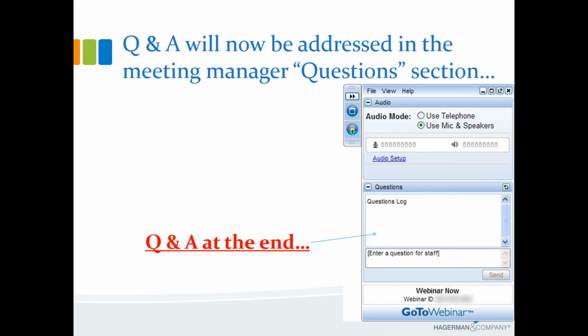Also, if you do roll them up and then you come back after you do that and you make an edit like I did where I used delete face and I removed a voided material, it's going to take that one item out of that line item because the length property just changed. So it looks at a couple of different things when it rolls them up. It's probably going to take that one item you make the edit to. If the length changes any, it's going to pull it out of that roll up and it'll exist as its own standalone item.